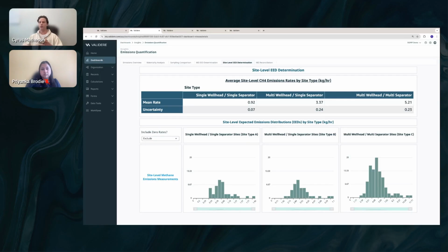So any uncertainty value that's being calculated here needs to account for the cumulative effect of the uncertainty from my statistical distribution, but also the uncertainty associated with the actual measurement values that I'm surfacing. What that means is as I begin to calculate results using these values, those uncertainties are going to propagate forward. So when I look at my cumulative OGMP level 4 or my cumulative OGMP level 5, I can evaluate what the uncertainty on those aggregate values is.